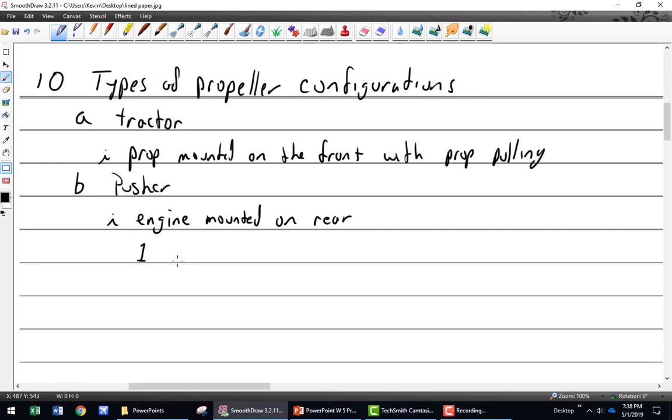Because there are several instances where pilots are grabbing both handles and going forward. You cannot hear the rear engine or see what the rear engine's doing. You can look at your manifold pressure, but what's your manifold pressure at takeoff? Near sea level. What's your manifold pressure when the engine's shut down? Near sea level. So your manifold pressure is the same at max power or off. Of course, your RPM should be working, but it's not something you're usually looking at during a takeoff roll. You're watching the center line and airspeed. You don't look over at the tach. You're just kind of feeling things.